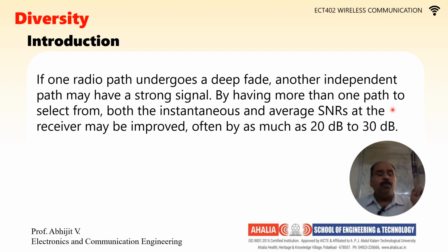By having more than one path to select from, both the instantaneous and average signal to noise ratios at the receiver may be improved by as much as 20 to 30 dB. So there is a minimum improvement of 20 dB in the power, and it can go up to 30 dB, because it mitigates the effects of small scale fading to a great extent.